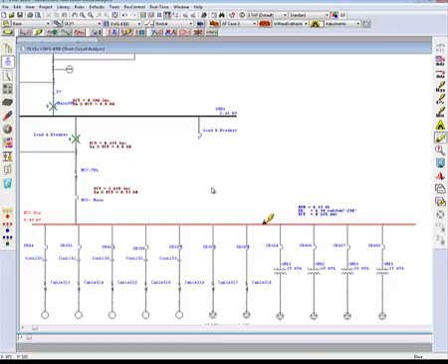Now, as shown on the one-line diagram flashing of devices, you can see that it's uncoordinated, or you're not being selective enough by clearing the MCC first. So now load A breaker is operating first, and then that main switchgear breaker, and then finally the main MCC at 2.62 seconds. Of course, the first device, which is the load A breaker, is the one to de-energize completely the fault.